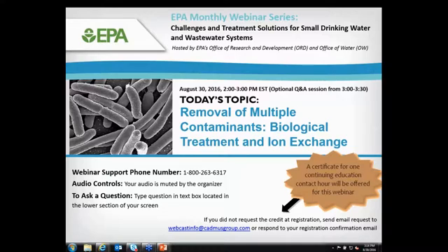For example, if your goal is to remove natural organic matter to minimize the probability of disinfection byproduct formation, that's something that, from an operational maintenance point of view, is much easier to pull off than anaerobic biological treatment in its current state. So it really depends on what you're looking at, and I'm optimistic that there's progress that's going to be made on the simplification issue over the next half decade or so.